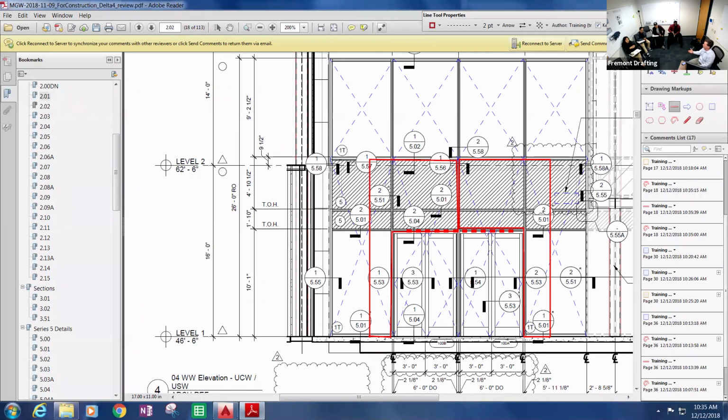And so it's not really a function of the door, but it's a function of the wind load on it. So we either put a 1/4 by 4-inch steel plate across and then we're bolting them together, or it might be something in the header. But we've got a corner of the unit that doesn't have any support, and it's just gonna wanna bend. We could put a kicker also, if we wanted to put an anchor here and kick it back up diagonally to the floor. So there's different things you can do. We can have a little Mac anchor right down there, taking that wind load back somehow.